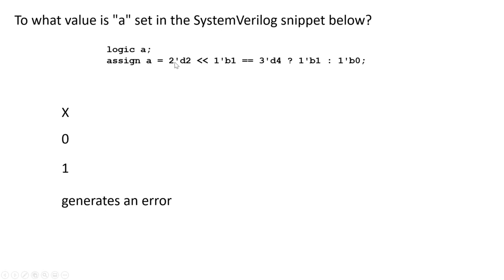Because see, if the expression evaluates to 2 bits, right, then 2 shifted by 1 bit to the left doesn't fit in 2 bits, right? This is going to be 2 multiplied, this is 4, but 4 doesn't fit in 2 bits. Or is Verilog going to assume that this sub-expression will evaluate to 3 bits because I need 3 bits minimally to represent the answer? Well, unclear, but let's just assume that it's going to say 3 bits.